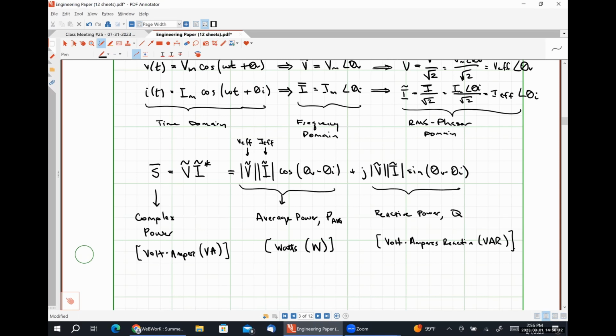Okay. So since the reactive power just represents power getting sent back and forth between the source and the load, well, why is it important? So without our utility grid having some temporary energy storage in it, anytime we experienced a surge in usage, so for instance, when everybody gets home at 5 and starts cooking dinner at the same time, we would have blackouts because there would be no energy storage to help accommodate that increase in demand, okay? So while the reactive power represents no net transfer of energy, it is critically important to the infrastructure of all industrialized nations, okay?